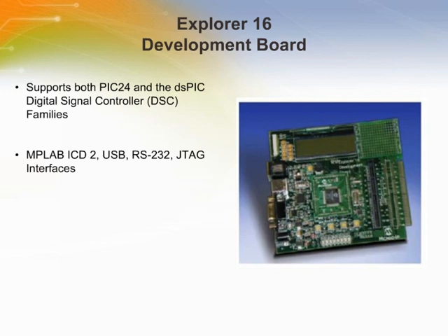The Explorer 16 board is designed to interface to the MPLAB ICD2 to provide a complete development platform. The board includes a PIC24FJ128GA010 and a dsPIC33 DSC. The processors can be changed by changing the processor interconnect module, or PIM.